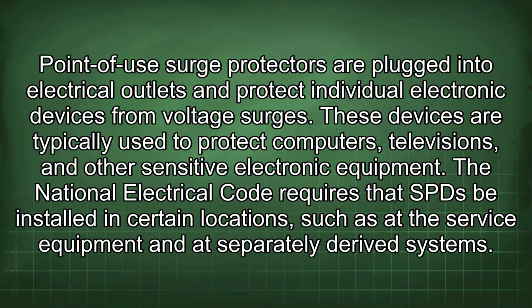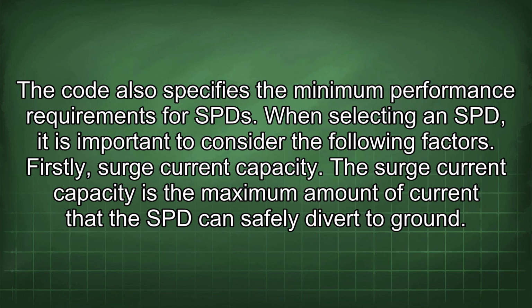The National Electrical Code requires that SPD be installed in certain locations, such as at the service equipment and at separately derived systems. The code also specifies the minimum performance requirements for SPD. When selecting an SPD, it is important to consider the following factors.